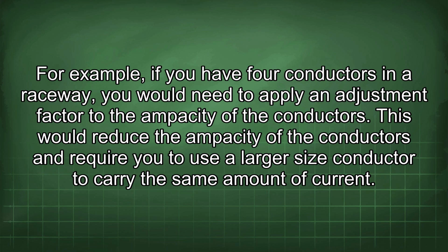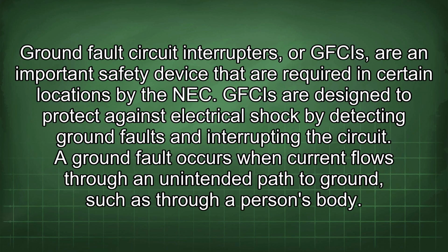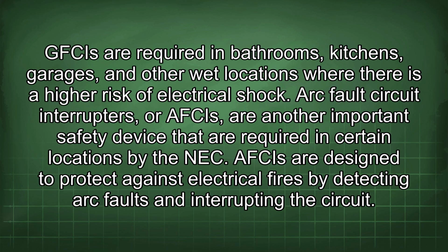same amount of current. Ground fault circuit interrupters, or GFCIs, are an important safety device that are required in certain locations by the NEC. GFCIs are designed to protect against electrical shock by detecting ground faults and interrupting the circuit. A ground fault occurs when current flows through an unintended path to ground, such as through a person's body. GFCIs are required in bathrooms, kitchens, garages, and other wet locations where there is a higher risk of electrical shock.